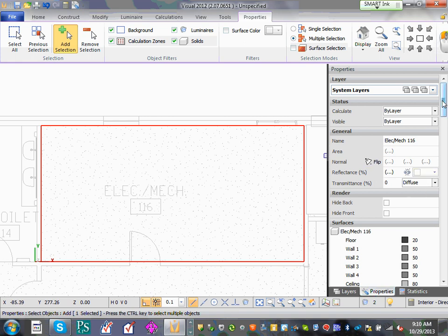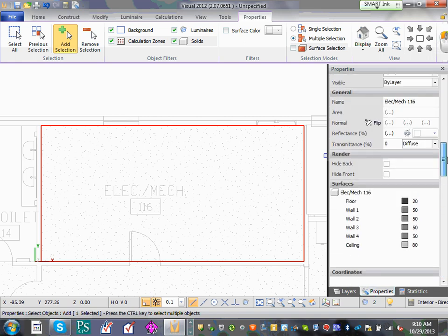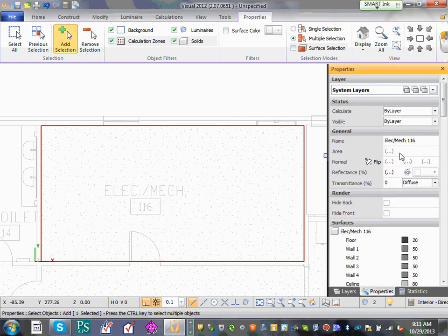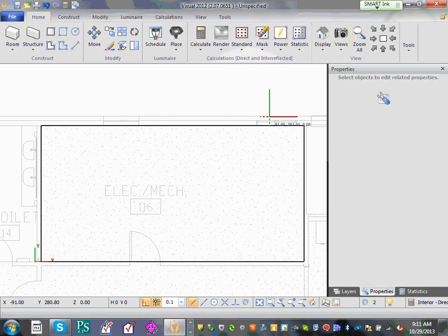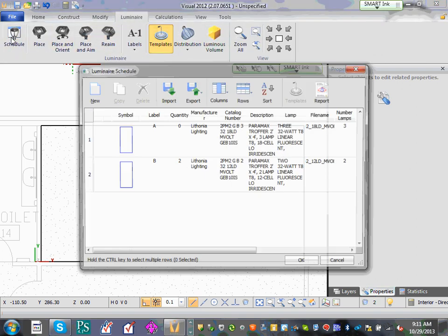All right, before we move to the next step with Andrew, guys, make sure everybody's room is set. Brian and Karen, cool, 13 foot, make sure it's 13 feet. Okay? Yeah, it looks like you just have to redo it if you have that. Or you could actually go to modify and scale and just scale on your Z-axis. Then you need a calculator.